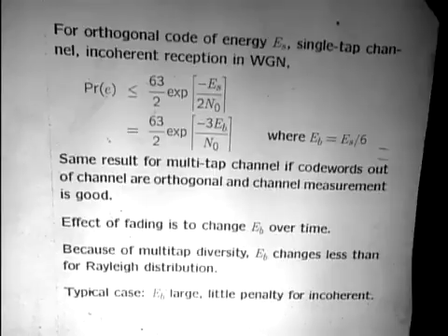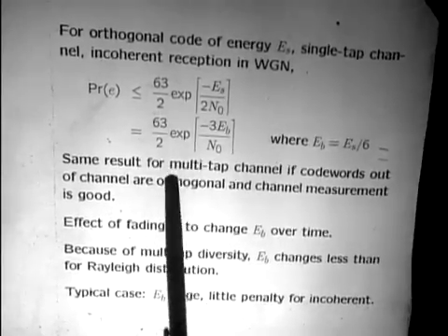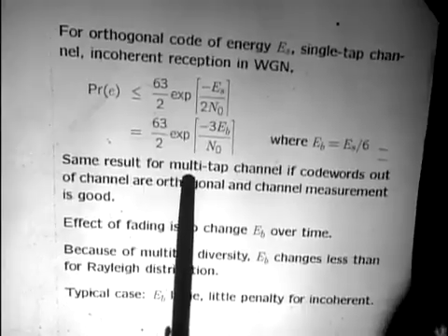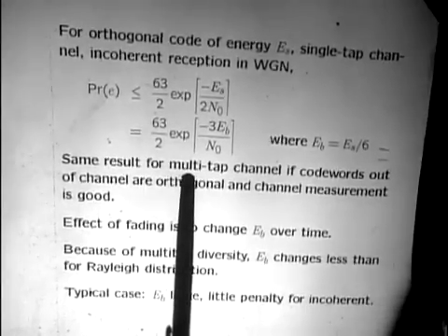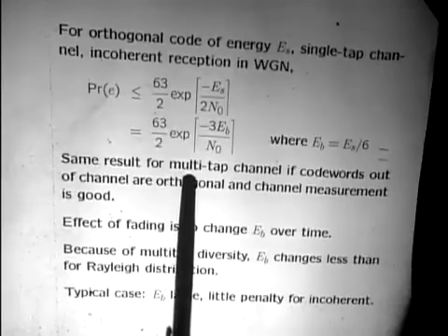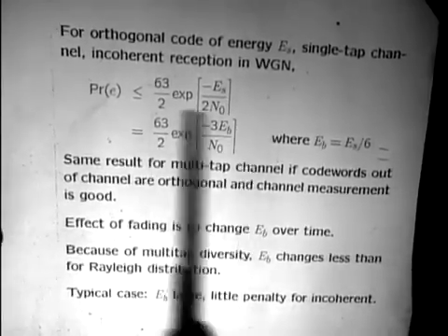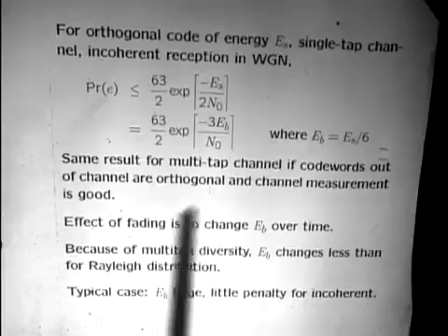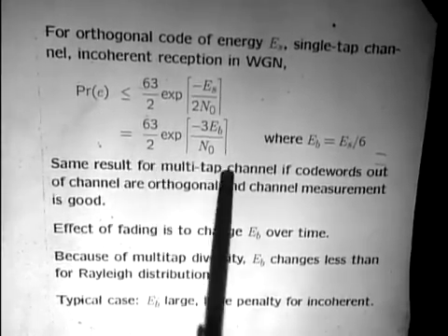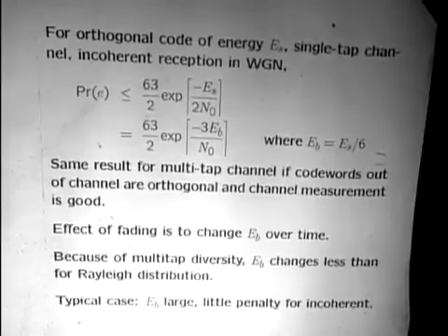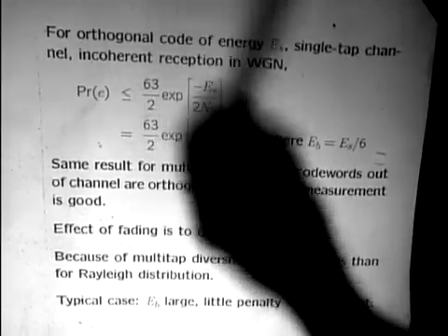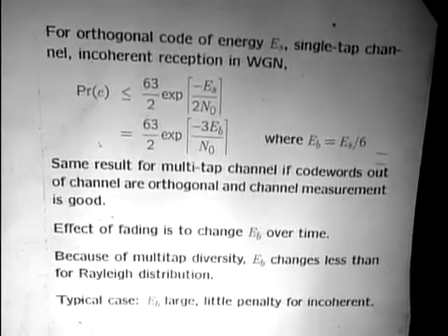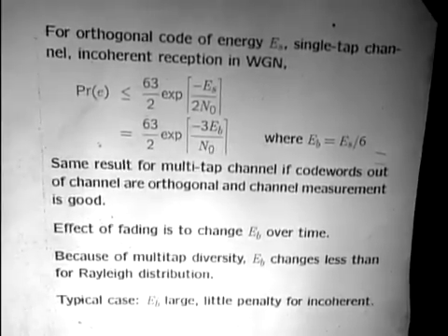and your decision comes out with very small error probability. Well, as it turns out, we're not interested in making these hard decisions. What we're really interested in doing is just sending a likelihood ratio back to this Viterbi decoder, which it can use in making final decisions. But to see how well that's going to work, this is exactly the thing you want to look at, because this is what's telling you if EB is large enough, your decisions, if you had to make them, would be very good. And therefore, if instead of making decisions you pass likelihood ratios on, those likelihood ratios are going to have a lot of information in them. I mean, essentially, those likelihood ratios tell you what those code words are.